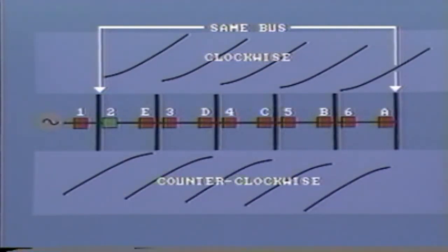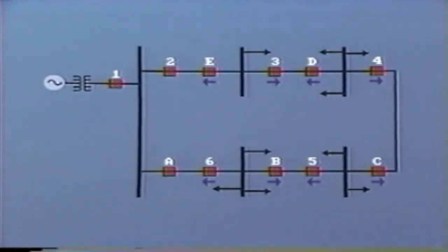Finally, operation of the whole protective scheme should be checked by assuming various fault conditions. This would include all breakers closed on the loop and the application one at a time of a fault at each end of each section of line. The calculated values of fault currents should be used for both maximum and minimum operating conditions. This study may bring to light certain minimum conditions that perhaps do not operate the relays as desired, thereby necessitating a re-examination of the relay settings.